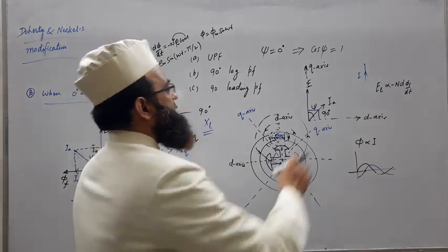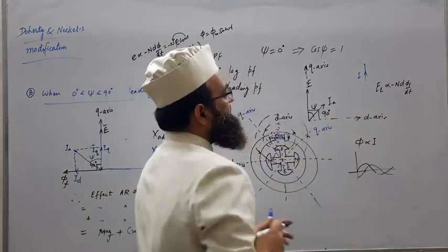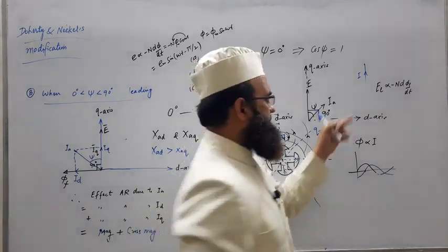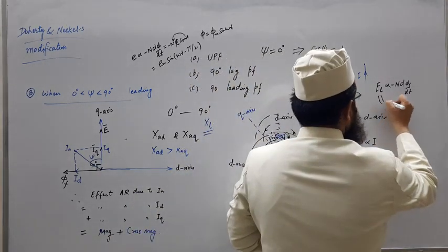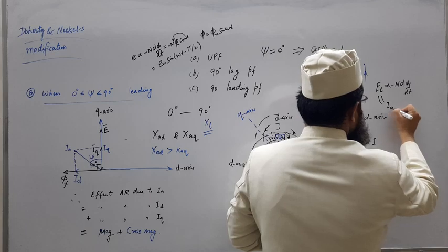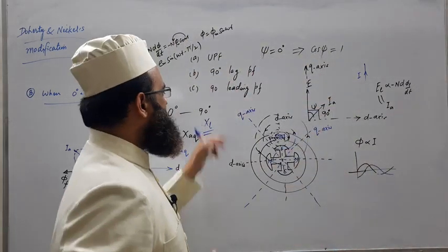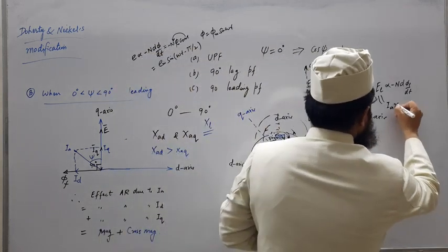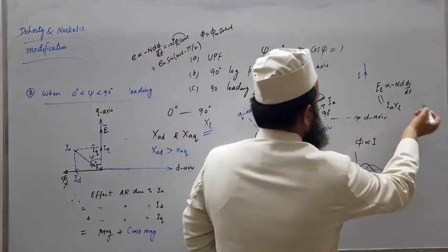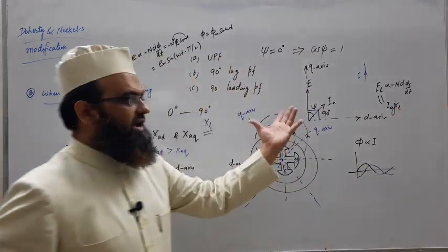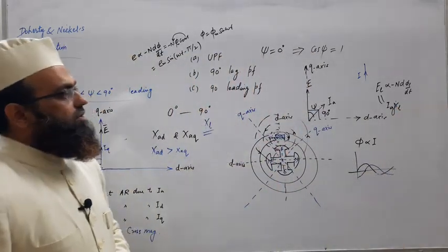Hence, while writing EL, this will be proportional to armature current, so EL may be written as equal to IA times one constant, and that constant of proportionality will be nothing but XL. Sign we will take care of later, jXL, plus minus, it is opposing, hence minus.